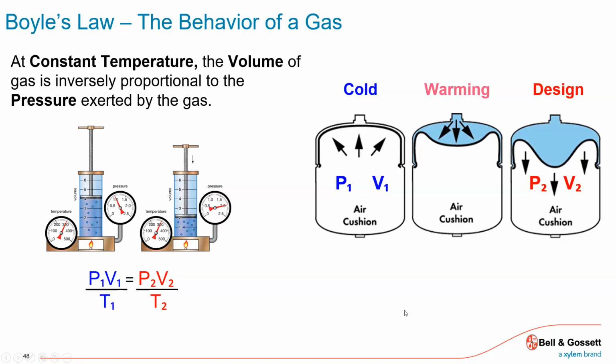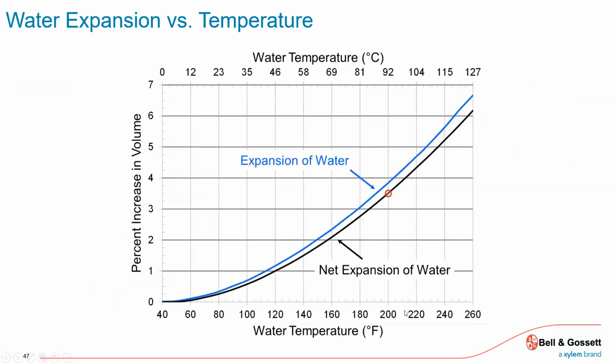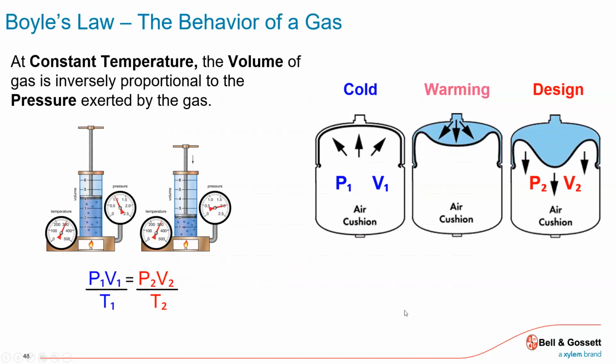When you attach it to the system and the system's cold, there's no water in that tank. That's how you sized it. That's how we want to size it. And then as they heat the water, that water expands. And as it expands, how much? Well, how hot's the water getting? There's my expansion factor. It's going to start to enter in and it's going to fill that tank.